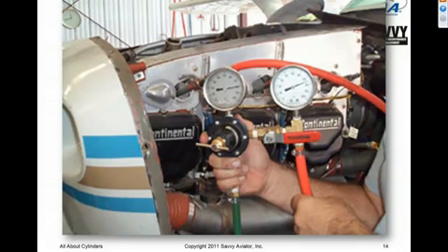particularly because when we're doing this, the cylinder is much, much cooler than it is during actual operation. And so we have this sloppy fit between the piston and the cylinder, and the rings are way out, sealing the gap between them, the annulus between them, and the rings have ring gaps that air can sneak through. So there's no such thing as a leak-free combustion chamber. So air is going to continuously leak out of the combustion chamber and have to be made up by more air being pumped in. And the greater the rate that we have to pump air into that cylinder to maintain its pressure, the greater the pressure drop across that little calibrated orifice between the two meters.